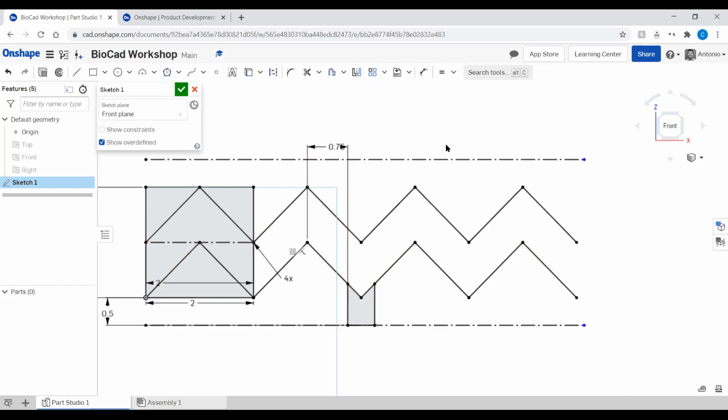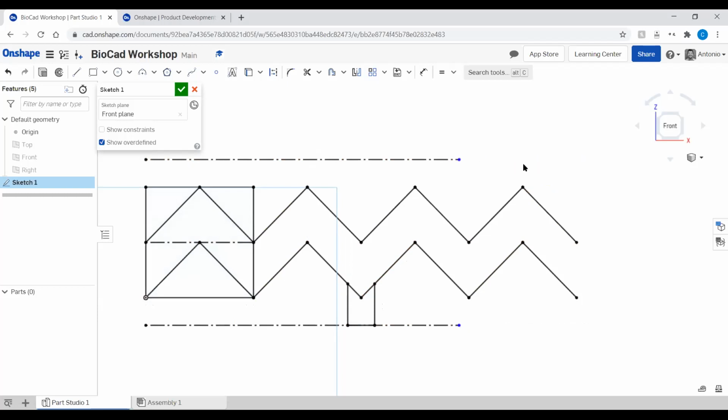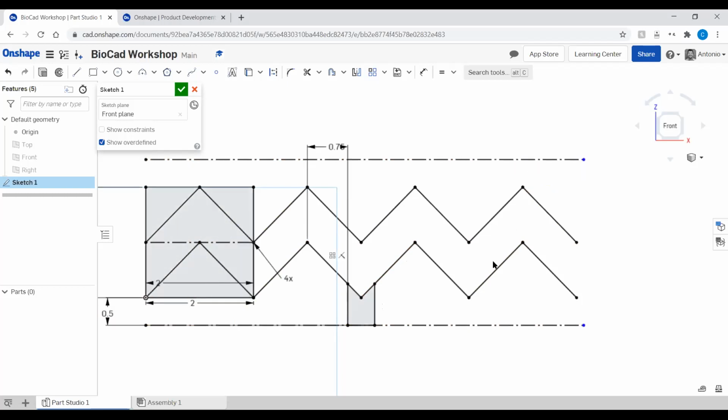Basically, what I'm doing is I'm making it so that now this connector here and this connector that we're going to make right here are exactly equal to each other. What's nice is, because I mirrored it rather than create a new line, if I edit this and move it, make it shorter, make it bigger, maybe space it away from this, they both move because I leveraged the fact that they're symmetrical. Does that make sense for people? Why it's better to mirror things rather than just create a new line.